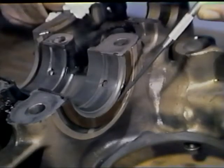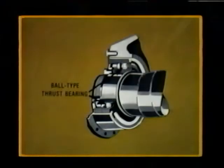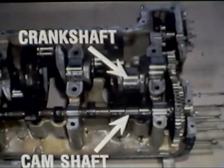Thrust loads are carried in some engines by a flange on the bearing, riding against a polished thrust face on the crankshaft. In other types of engines, ball bearings riding in deep races carry thrust loads into the crankcase. The crankcase is designed to have sufficient rigidity to hold the crankshaft and camshaft in perfect alignment for their smooth operation.